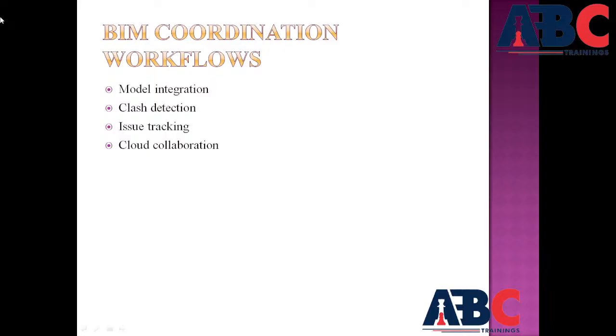After that, issue tracking and resolution. Once the clashes and inconsistencies are detected, they are documented and assigned to relevant team members in the issue tracking system within BIM 360 or a similar platform, so the design teams make corrections in their respective models.